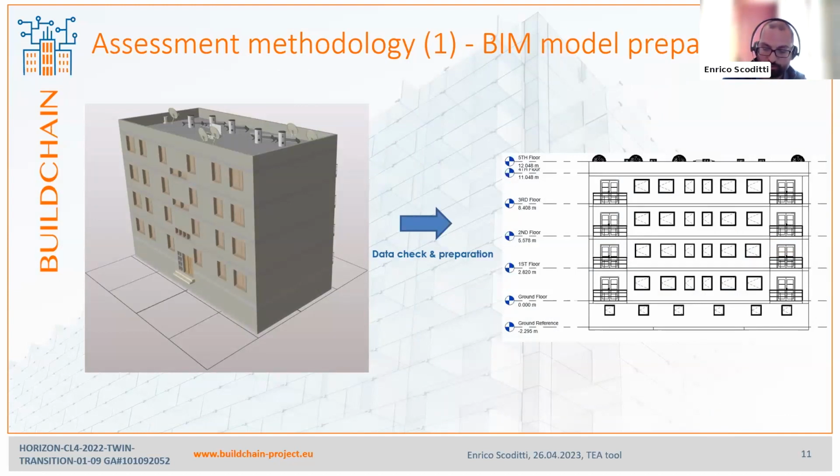The BIM model should comply with some simple modeling rules. For instance, the BIM model should be created with respect to a story-based modeling approach. This means a BIM element should belong to only one level. A wall object, for example, should not link more than 2 levels.